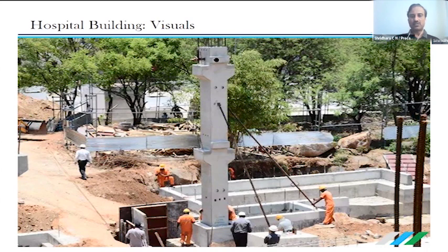You can see this is a 2-floor single column, and all these brackets, corbels as we call them, are created to rest the beams at first floor and second floor level. We can even go 2-floor, 3-floor single columns, and sometimes single floor also. It all depends on design and on the logistics available at the site. The design department has to take a decision before finalizing their design as per the site and design requirements.